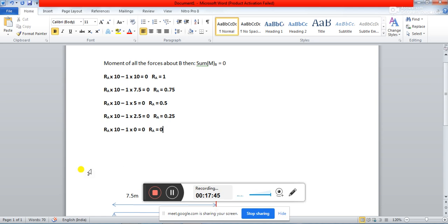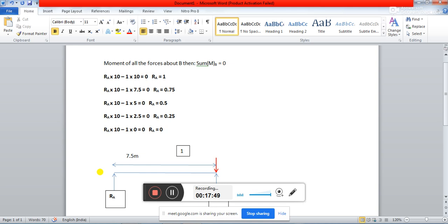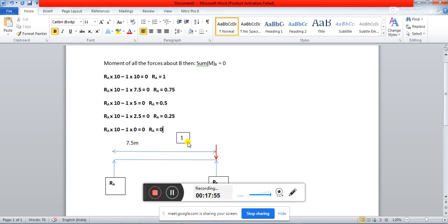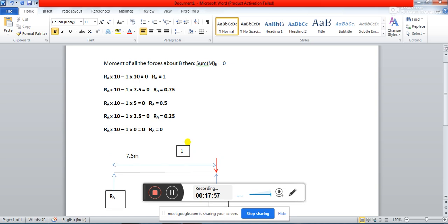So what have we done exactly? What is the difference between the influence line and the bending moment diagram, shear force, bending moment, or reaction calculation? In case of reaction finding for a fixed kind of load, you will have to do this activity just once, but in this case you need to find it multiple times. After this there is no other way, the load will move out of this beam, so you will not have any reaction.